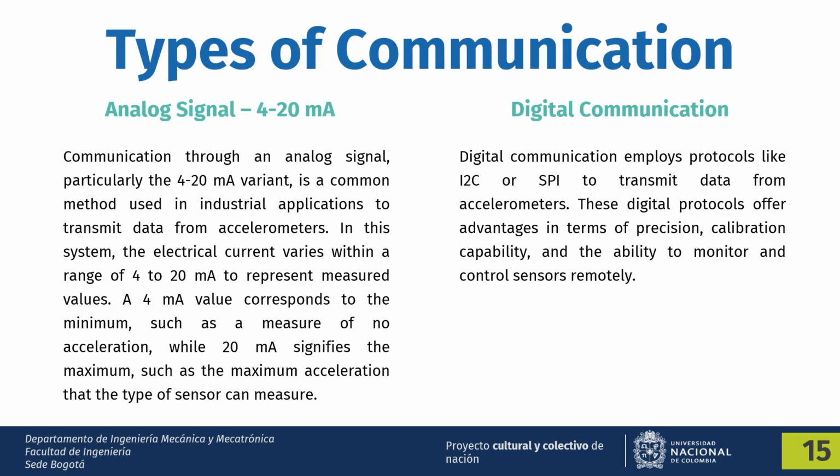Accelerometers with an analog interface show accelerations through varying voltage levels. These values generally fluctuate between ground and the supply voltage level. An ADC on a microcontroller can then be used to read this value. These are generally less expensive than digital accelerometers, although in industrial applications it is customary to use a current signal instead of voltage because the signal won't change over big distances.